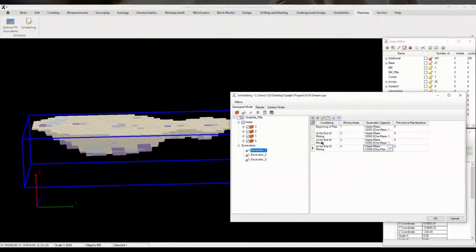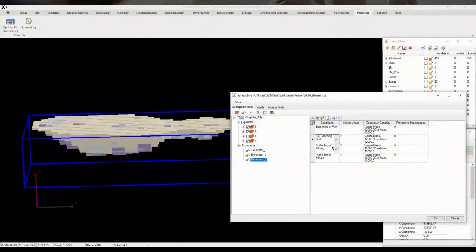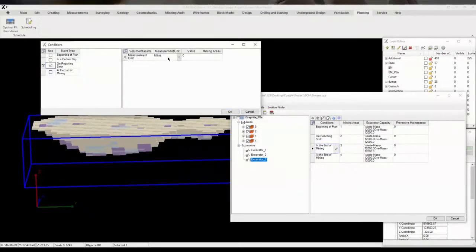So we will calculate and get instant results. The interval will show which blocks are processed in each time interval. The results are visual information about the blocks, tabular data, and daily visualization of mining. Also, it's possible to upload the resulting data in the form of polylines and wireframes, but more on that later. As I mentioned earlier, this type of planning can be used as a forecasting tool or the final stage of the planning after determining mining areas in a specific period that is obtained as a result of the search for solutions.